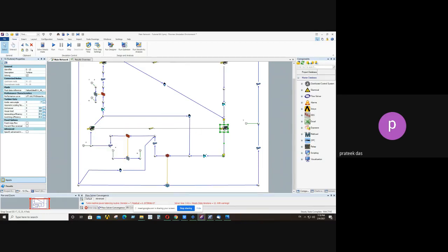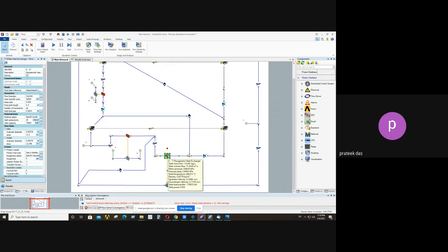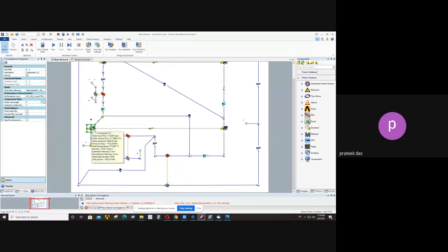So after expansion in this low pressure turbine, there is a recuperator type heat exchanger, which is going to exchange its heat with the incoming cold helium, and after losing heat, it again goes through the intercooler, in which it tries to reduce its temperature and increase its density, so the compression process will be easier.